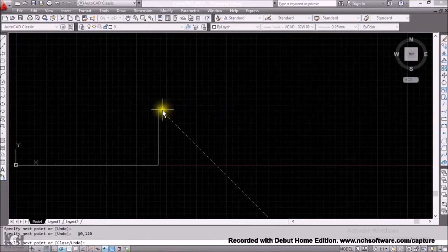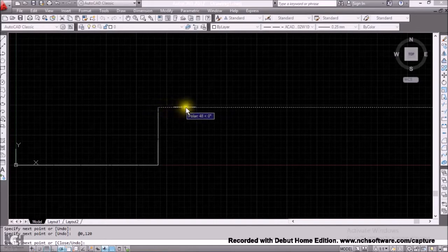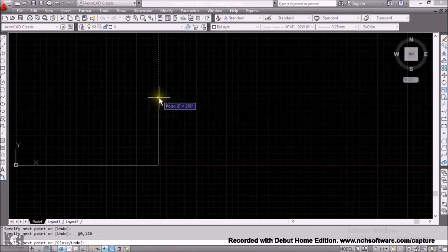So if I'm going along this direction and here is now my origin, that means the value of y is now 0. Assuming I'm going up to a distance of 150 millimeters from this new origin, following this method, y is 0 because you're not going up or down. So you have to issue the command at the value of x, which is now 150, comma the value of y, 0. You press enter on your keyboard.